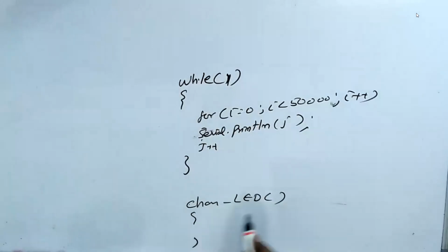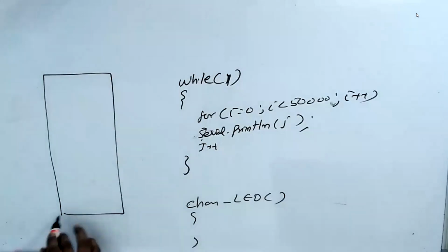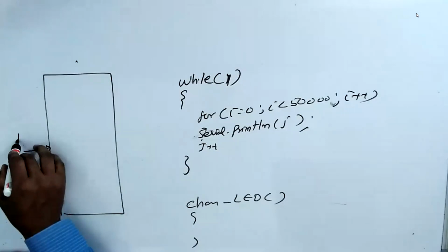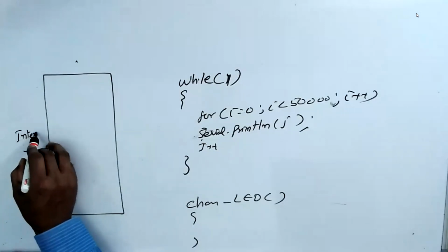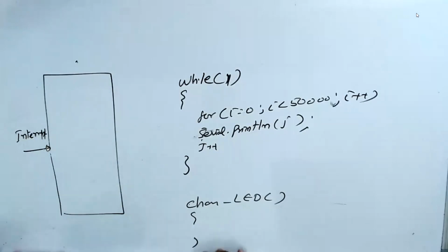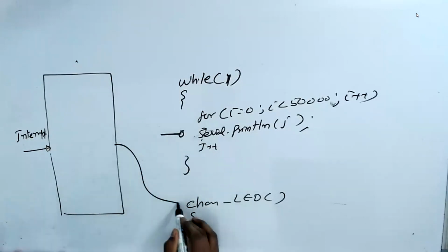Who is calling the function? That's a trick. Now, the function is called by a signal into the microprocessor. This signal is called interrupt. When the interrupt comes, then the microprocessor will stop this, go here and execute this, and come back to this.